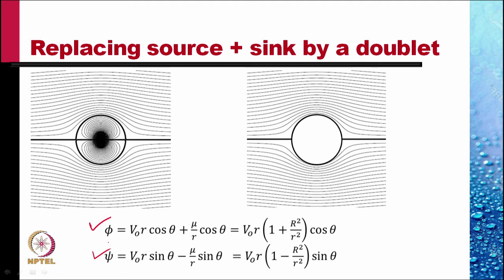We had also calculated the velocity distribution on the surface of the cylinder, and using this velocity profile, we had calculated the pressure distribution using the Bernoulli equation. If the flow did not separate over this cylindrical surface, then that is exactly the pressure distribution that we will get, or that is approximately the pressure distribution that we will get. But the flow does separate over a cylinder. It would not separate if the body was streamlined like an airfoil, and in that case the predicted pressure distribution would be the same or very nearly the same as the actual pressure distribution.